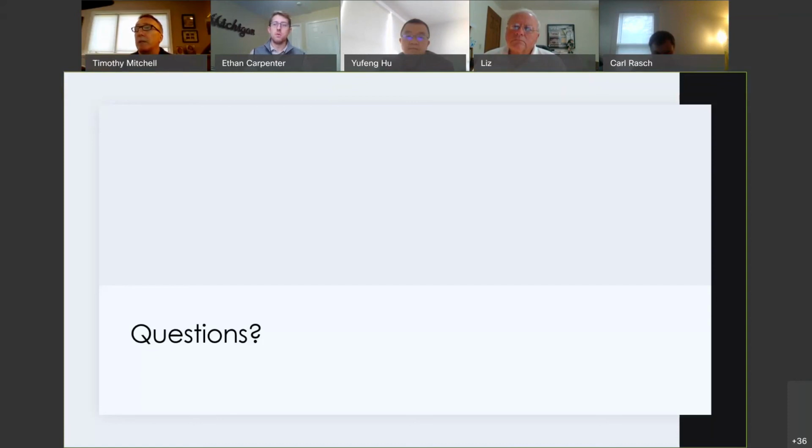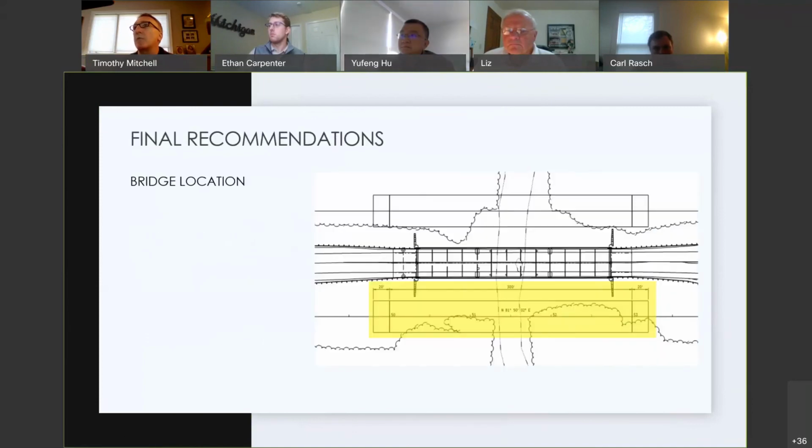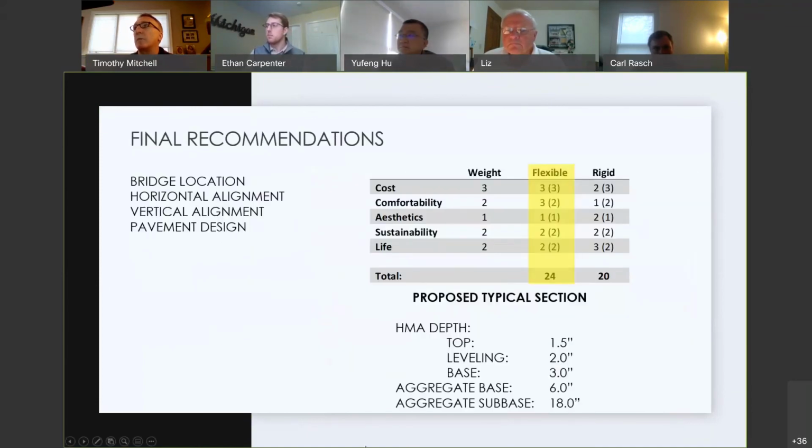Okay, yeah, that makes sense. I probably missed that part. The second question I have is, did you consider the differences, or why you were getting the differences of a 3-inch asphalt thickness, which seems awfully light to me? I don't know what the truck traffic is, but it's a state route. And the 6 inches, or 6.5, or whatever it was that you ultimately came up with, it just seems like there must be something in the calculation to come up with 3 inches that maybe was not right.